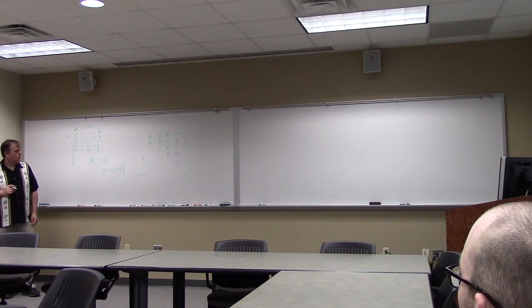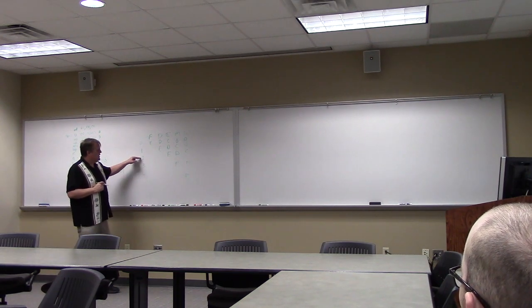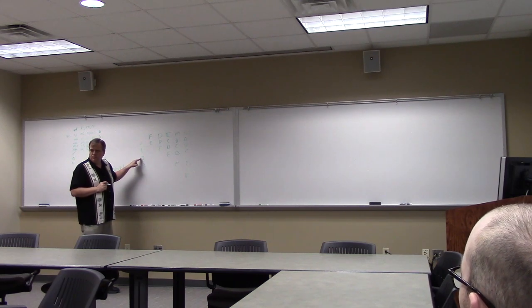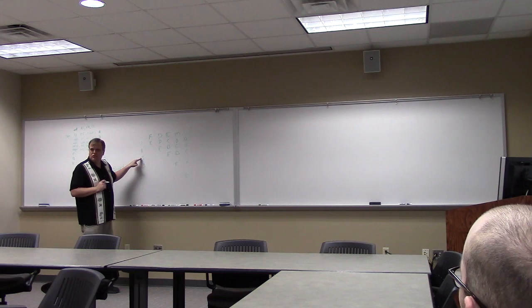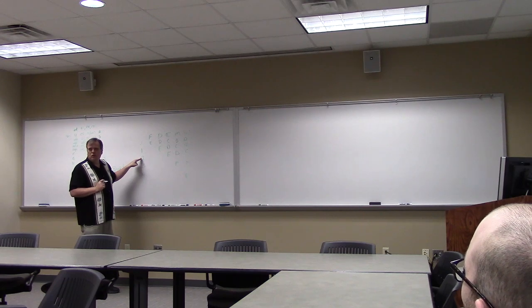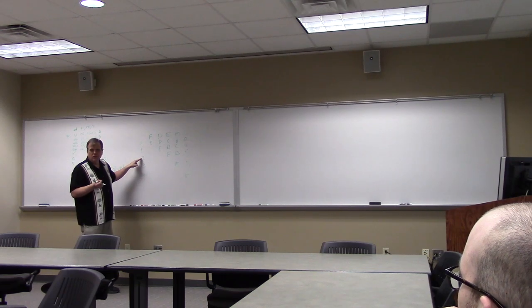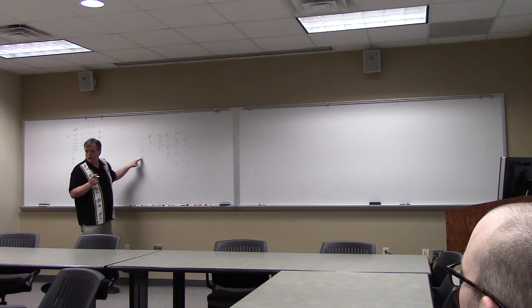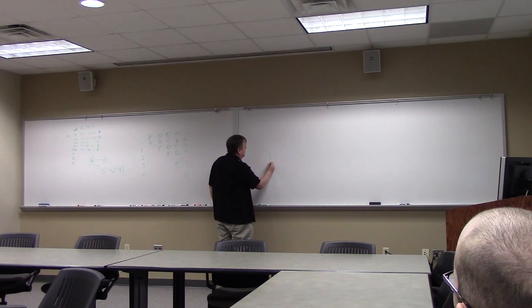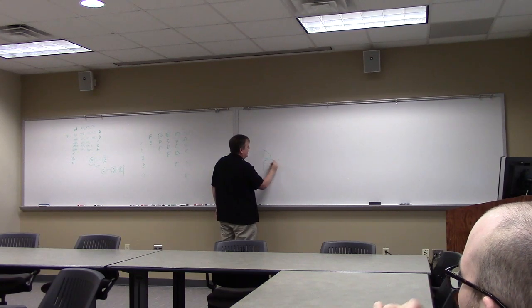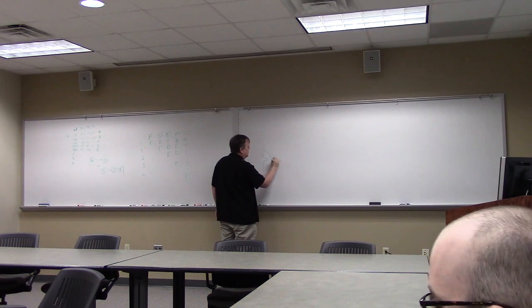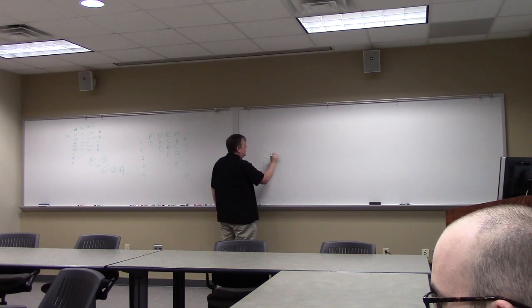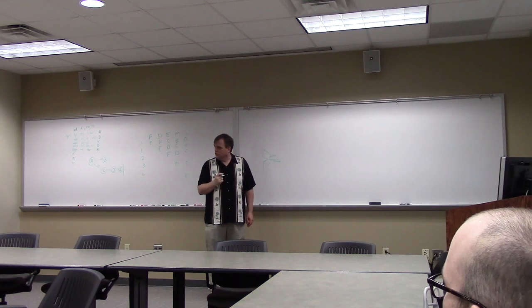At the end of execute? So, it does at the end of execute, it's done the calculation. But for a MIPS machine, it hasn't taken that result because it took the entire period to get the answer for doing the comparison. So it outputs a 0 to you. And then you've got to do 0 and branch in order to determine should I really jump. So your ALU in the execute phase has the output of the result, and it also has another line called zero, which was the result equal to 0. That's what's used for branch not equal.